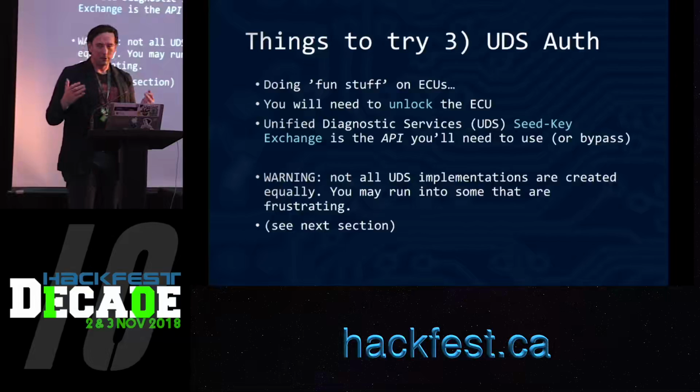So first up is UDS is a 16-bit challenge response, which means that you can actually extract the lookup table for this thing, right? I mean, if you have diagnostic software, you can fake being an ECU and just keep sending different seeds and extract the entire lookup table, and then take that, and anytime you want, you get a UDS session. But of course, you need that software and the time. This is a great example of a student who just set up a 4-way extraction of all the challenge responses to get it done in a week, which is pretty cool.